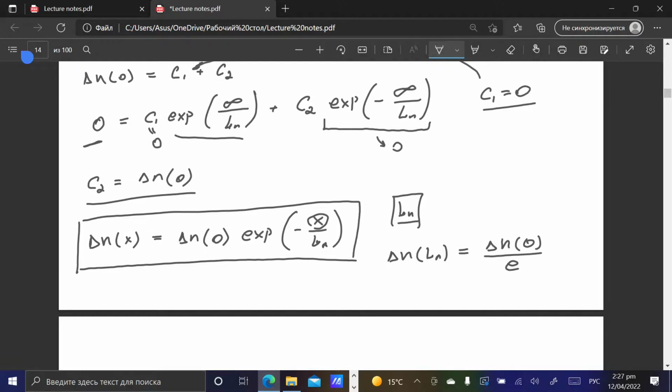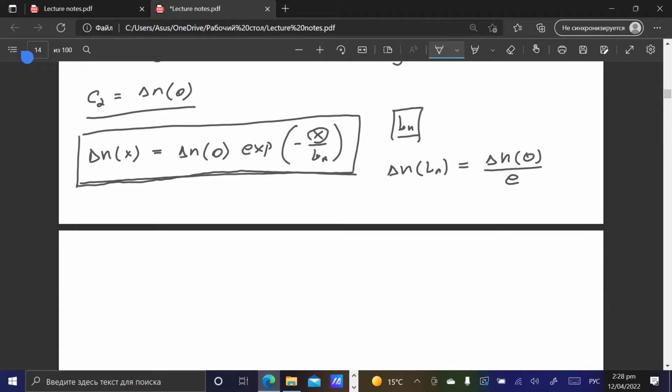So now that we keep in mind this profile distribution, which is very important in the derivation of the current-voltage characteristic of a p-n junction, because, as I mentioned, the key feature which defines the current-voltage characteristic is the distribution of these injected minority charge carriers in the respective regions of the p-n junction, we can proceed further and define certain conditions in the framework of which we will derive equations for the current-voltage characteristic of a p-n junction.